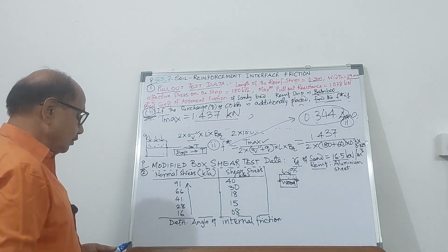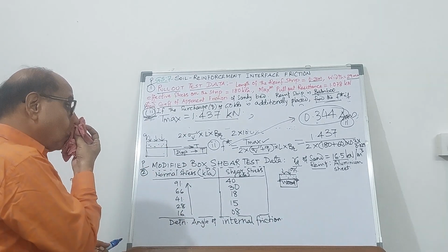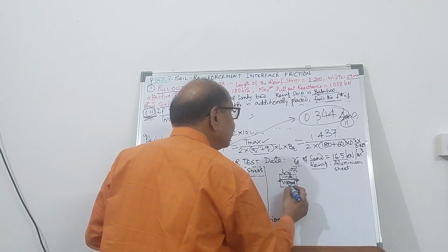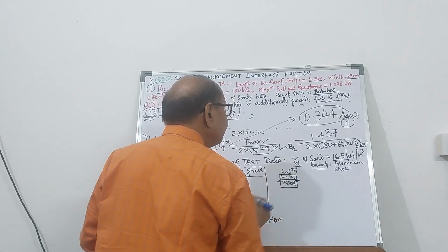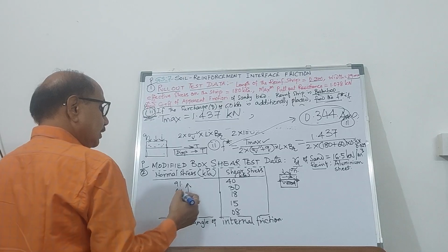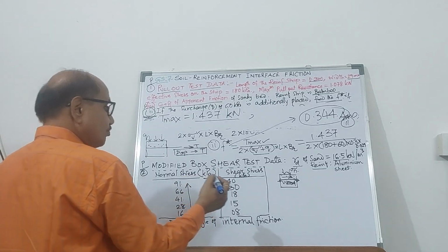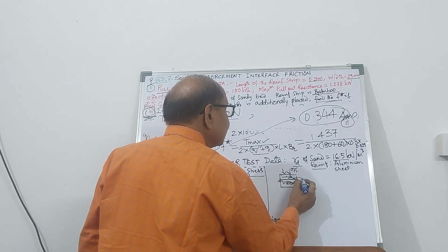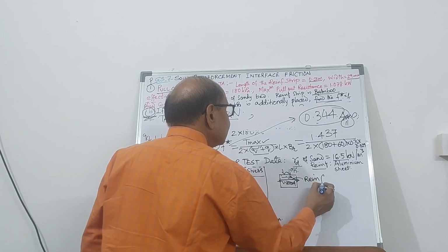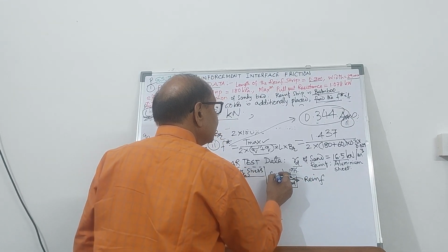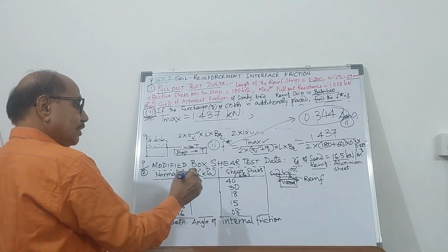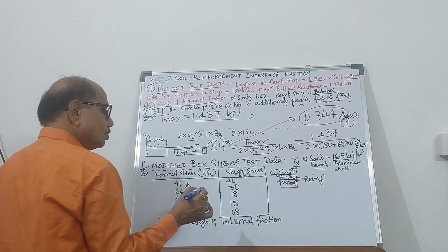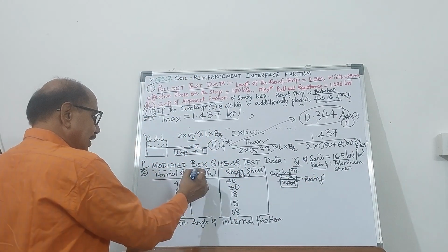So it's increasing, and when you are going to shear it, when this is going to move like this, then you are going to have the interface friction. The interface friction is called the angle of wall friction, that is between this reinforcement and this sandy soil. So this is the sandy soil. Here the unit weight you have maintained, and the reinforcing element is an aluminum sheet, and these are the data available to us.